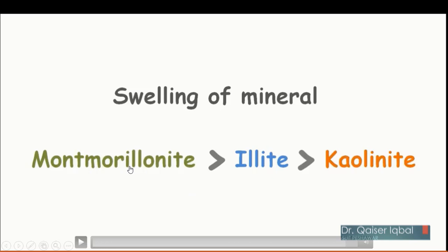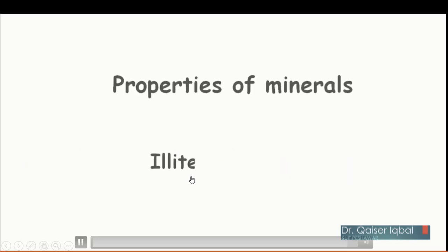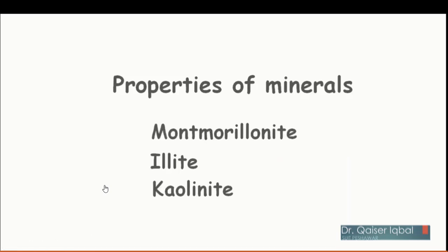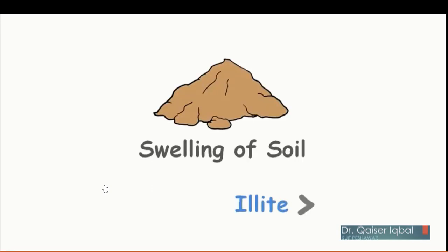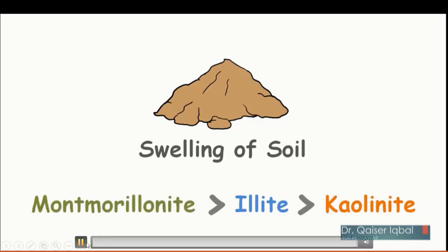It will have very high swell potential, Montmorillonite, and kaolinite will have very little swell potential. So in kaolinite you will have less volume change, and in Montmorillonite you will have more volume change. The kaolinite will have the least swelling, as I discussed earlier, and Montmorillonite will have the greatest amount of swelling. Okay, so now moving on.